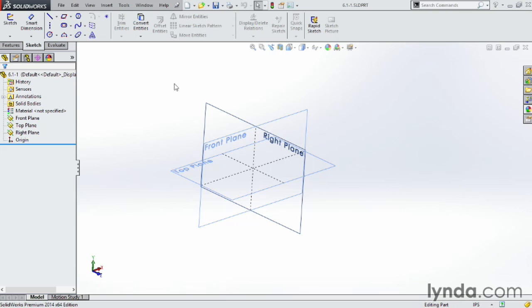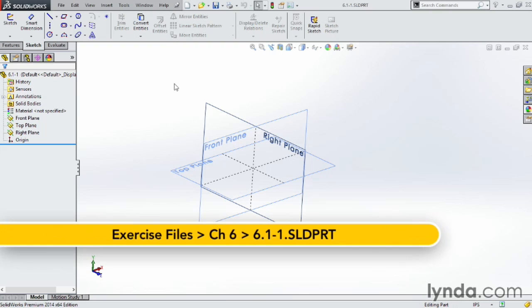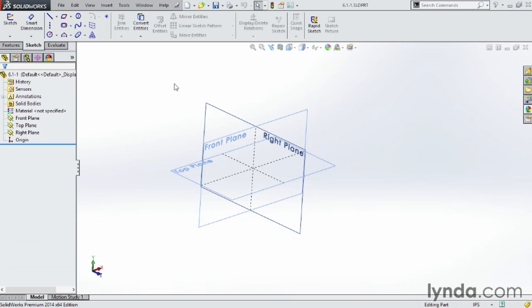When a new SolidWorks part is opened, we have 3 predefined planes to start building our model. To start a sketch, we need to choose either a face or a plane. But when you first get started, there are no faces, so you have to choose one of those 3 fundamental planes. So what happens when I need a plane that's other than the ones located at the origin?